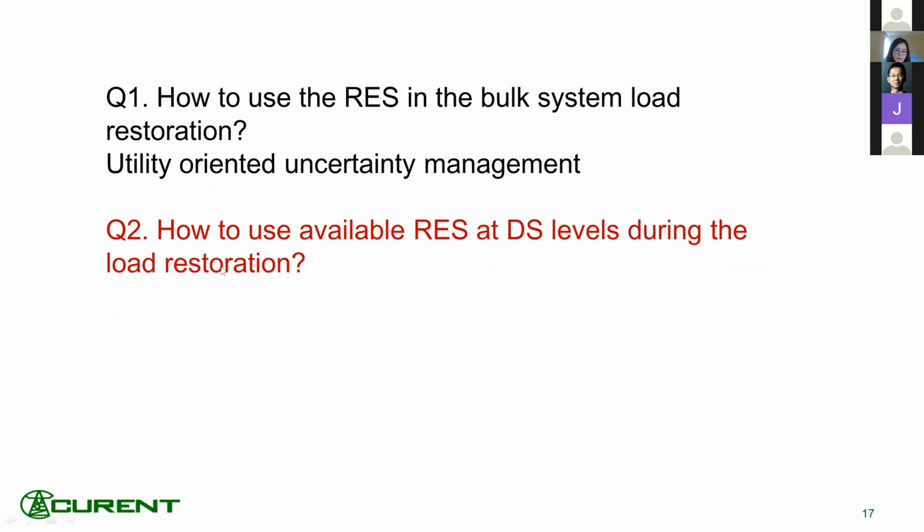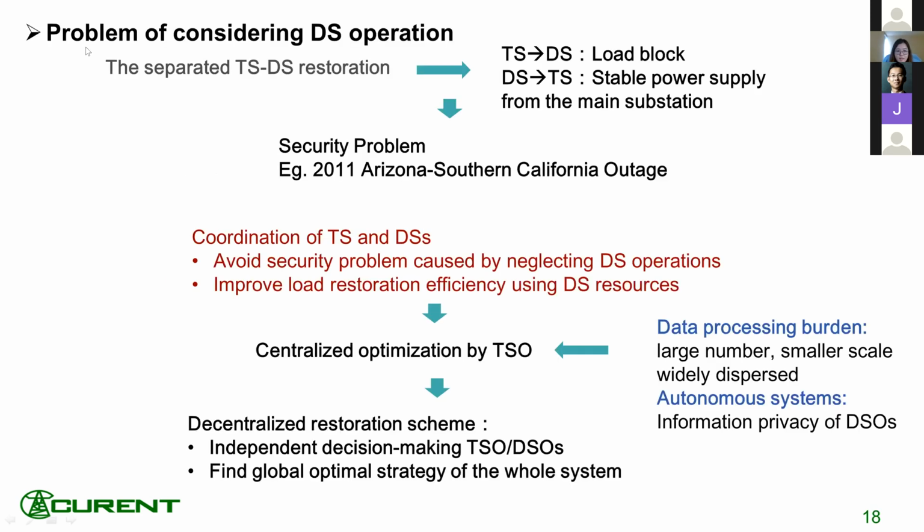Okay, so by using a utility-oriented management method, we have given a good guide about how to apply the IES in the bulk system. However, we all know that a large amount of the IES are actually concentrated at the distribution levels as distributed energy sources. So we may use this part of the sources to further speed up our load recovery process. And here come some